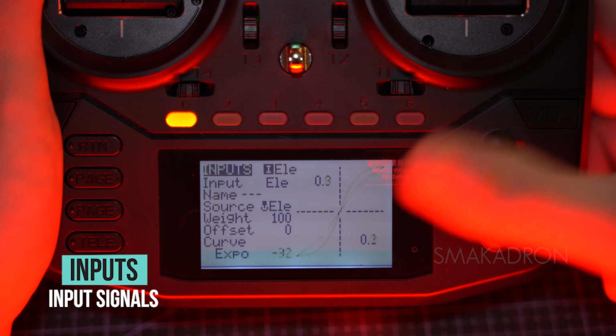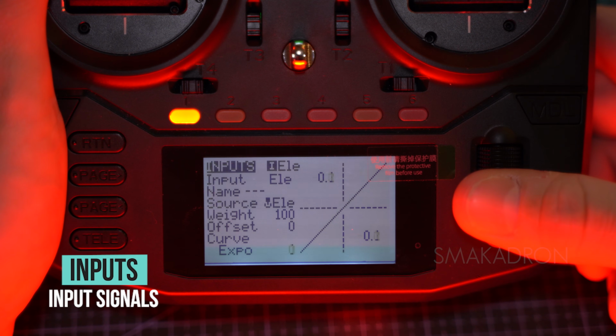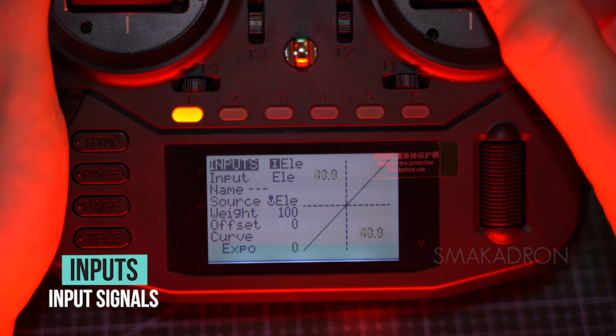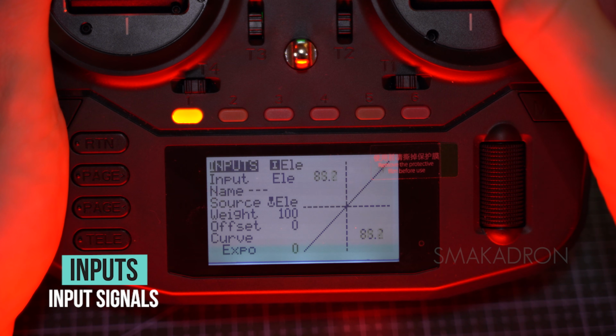Expo allows you to reduce the stick's sensitivity near its center position. This makes the model less responsive to small stick movements, which can help avoid accidental or excessive movements. Reducing sensitivity near the center of the stick helps the pilot make more precise corrections, especially during flights that require high precision, such as navigating through narrow spaces or during landing. Although sensitivity near the center is reduced, Expo allows you to maintain high sensitivity at the edges of the stick's travel. This means that with large stick movements, the model responds quickly and energetically.